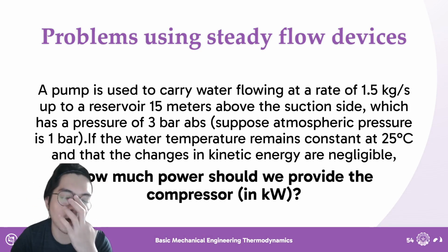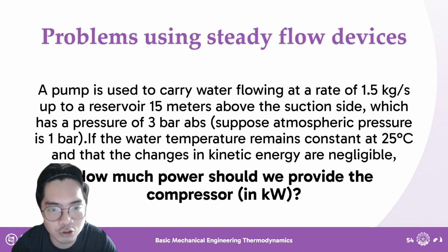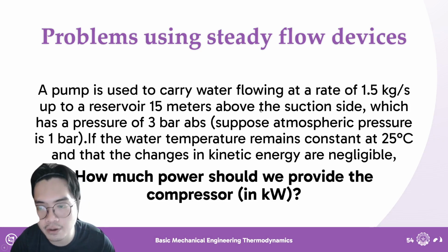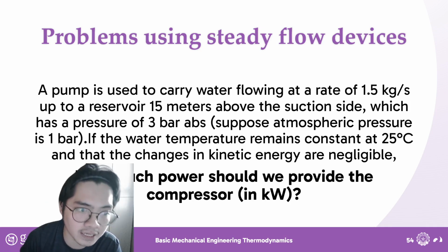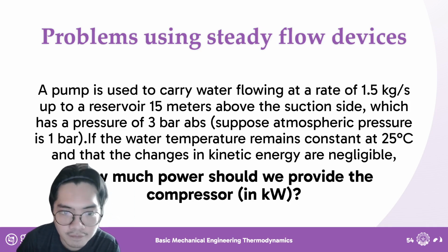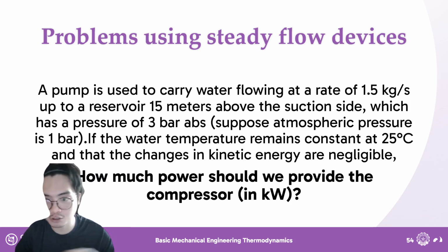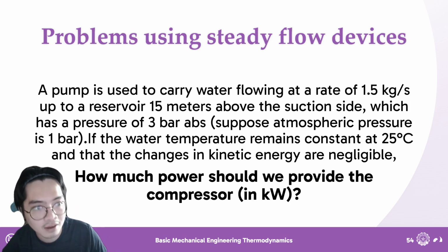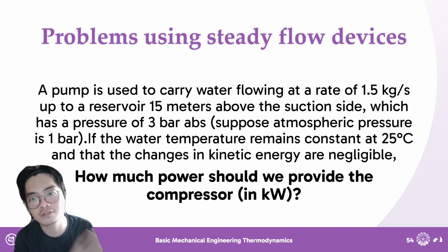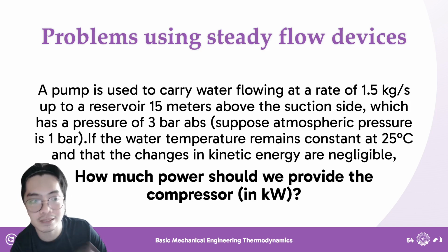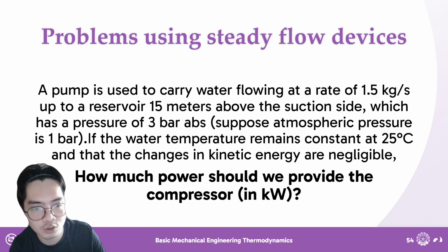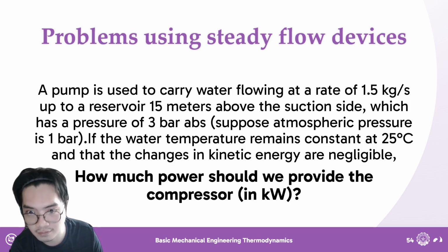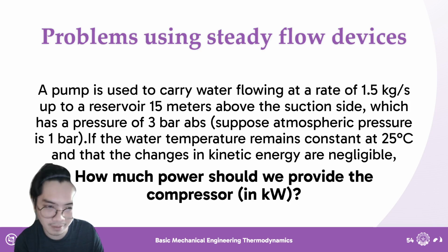A pump. This one, right? A pump is used to carry water flowing at a rate of 1.5 kilograms per second up to a reservoir 15 meters above the suction side. A pump has 2 sides: a suction, the one where it sucks fluid in, and then discharge, the discharge side where it spits it out, which has a pressure of 3 bar absolute. Suppose atmospheric pressure is 1 bar.